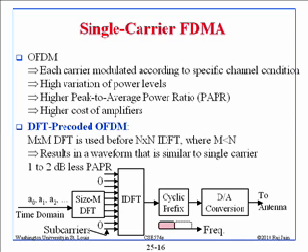Alright. Now, when you see here, this looks like a single carrier, because this whole carrier is totally used. But the way we got this single carrier is by doing a Fourier transform and an inverse Fourier transform. Now if you didn't have single carrier, then all we do is take this and convert it with an N by N discrete Fourier transform, right, for OFDMA, and we connect all of the pins to all of the pins. In that case, you get the subcarriers here. So basically the idea is that instead of having this full DFT, we have a small DFT. This is called DFT pre-coded OFDM, because before we went to the OFDM part, we had DFT pre-coding, right?